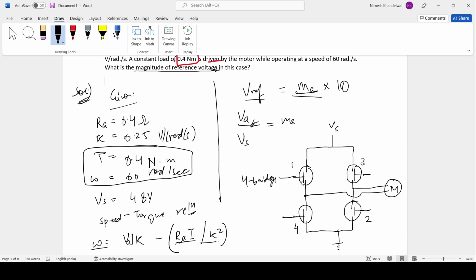It is as given in the question, and you have seen it in the theory also. We never operate the switches on the same leg at the same time, otherwise we are just shorting our source to the ground. Essentially we're just shorting our source, like let's say it's the battery or a voltage supply.